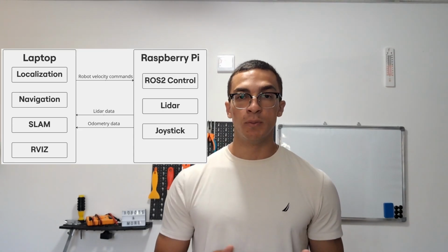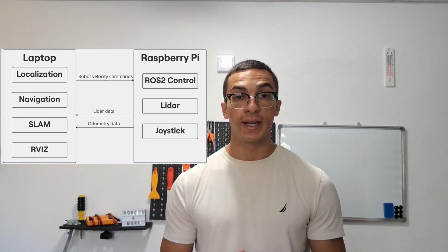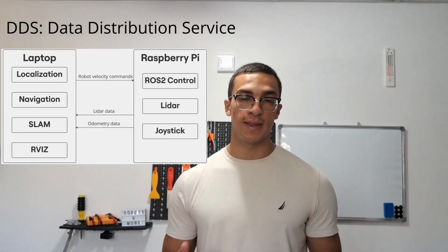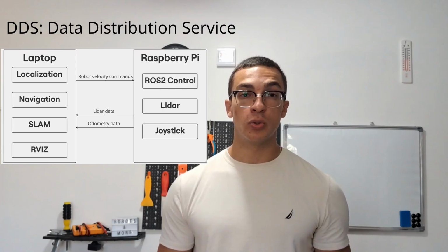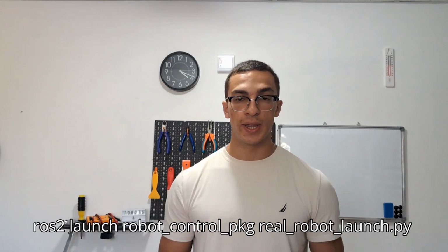Both the Raspberry Pi and the computer are connected to the same Wi-Fi network, and the communication is handled automatically by ROS2 middleware using DDS. This allows the nodes running on both machines to exchange information without the need for manual networking setup. A single launch file is used to enable both the differential drive controller and the LiDAR node.